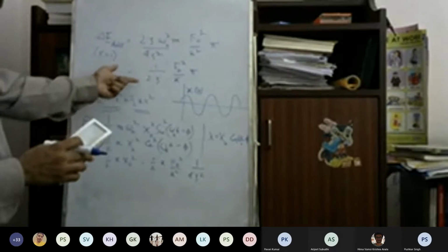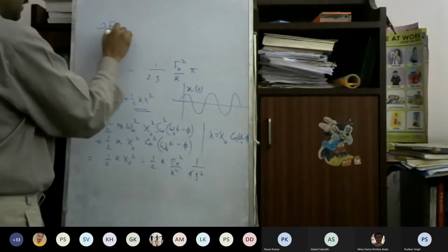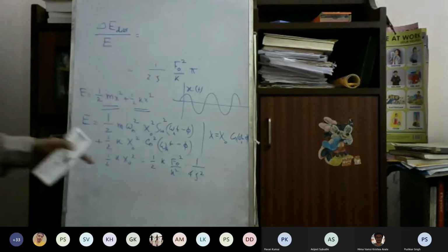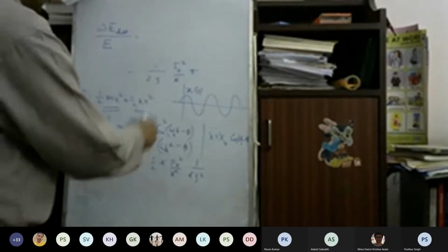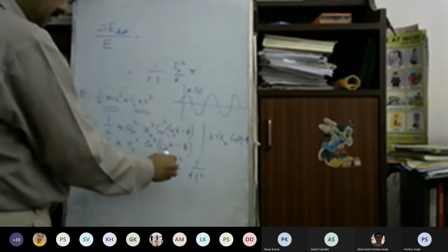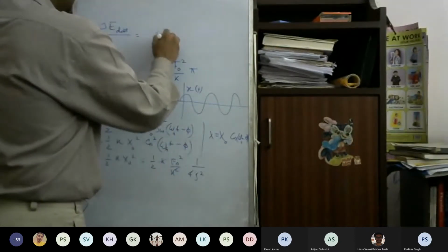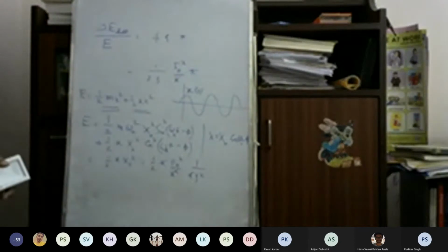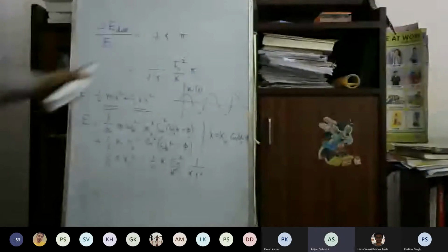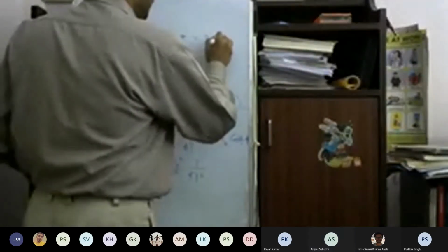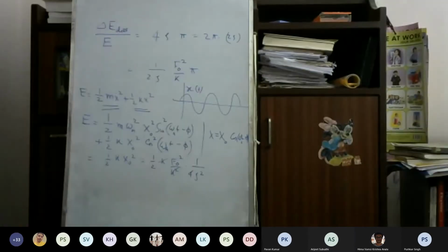Now please remember energy dissipation. So now I write this one as energy dissipation divided by E. This becomes equal to f naught square, so that part will be there. This is energy dissipation per energy. That will be pi f naught square will cancel out, half. So therefore 4 times zeta times pi. Is this correct? Can you check? Yes, sir. Okay. So 2 pi times 2 zeta.